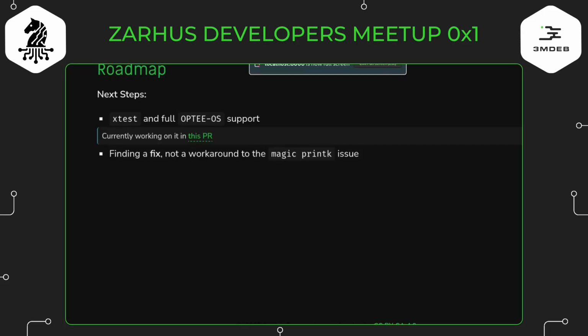When I was working on the integration, I came across this big problem where I thought everything was finished, but suddenly the OS was just at some point during the kernel booting, it was just stopping, and I didn't know what was the cause. There was no errors or anything, and I was stuck on this for quite some time, but a fellow from the CROSSCON consortium pointed to me a workaround to this issue. Turns out if you pick a specific abort handler in the CROSSCON hypervisor and add a debug statement there, just a print new line, it appears to keep the output going and allow us to log in.